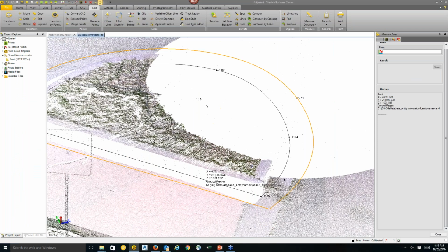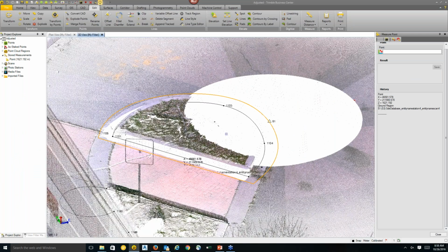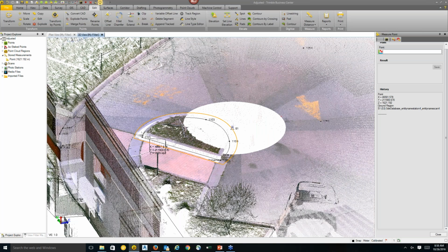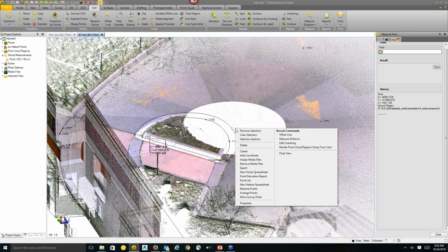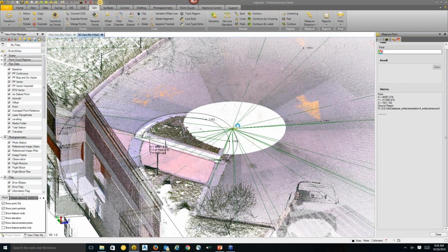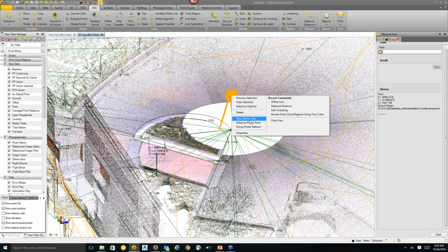All right. So one of the quick ways to extract geometry is using the station view, and maybe Riley can show us the virtual DR. Yeah, so what we can do is find a station. Let's turn on the raw data here and the photogrammetry data, and we see there's a station here. You can kind of tell by the missing point cloud, a hole in the ground, because the station isn't able to see in the near vicinity to where it's set up. We can select that station and right-click to open a new station view.